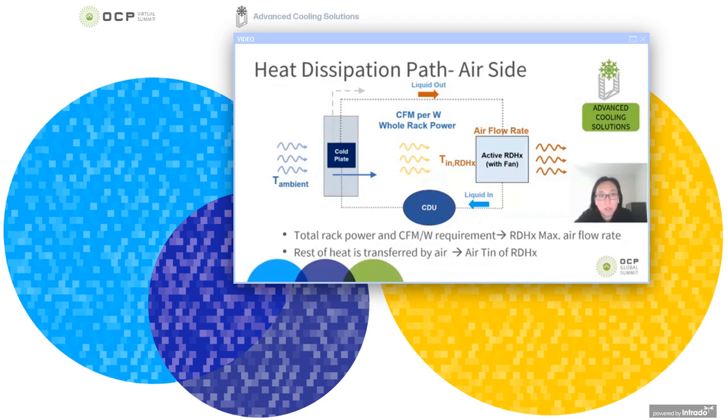At the air side, the cold air from the DC goes through the rack and each of the chassis, and carries some of the heat from the other components, which are cooled by the air directly. Then the preheated air goes through the rear-door heat exchanger to cool the coolant and becomes even warmer, then is exhausted to the hot air side of the data center.